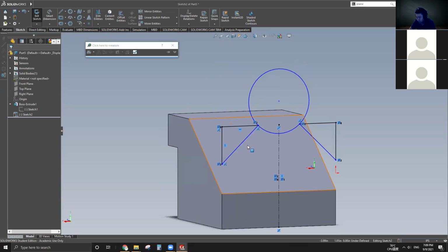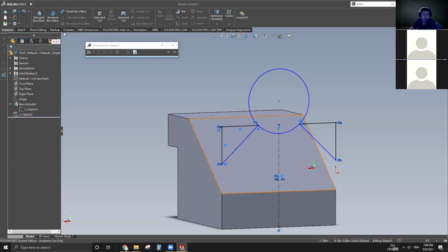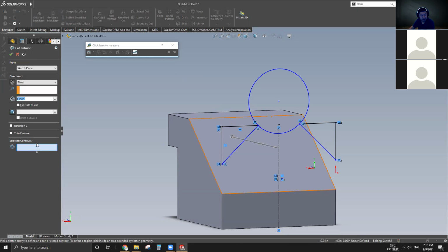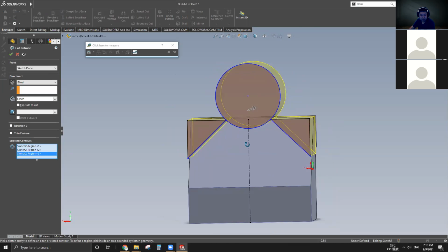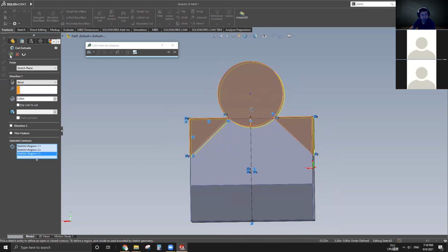We're ready to cut it because the contour first, second, and third are all enclosed. And we can make this circle have an extra line to right here and remove all the other extra parts of the circle. But in this case, we're just removing more unnecessary material, and that's acceptable. And let's extrude cut it. And from the contour, we select this, that, and that. Total 3, right? 2 triangular pieces and 1 circular piece.